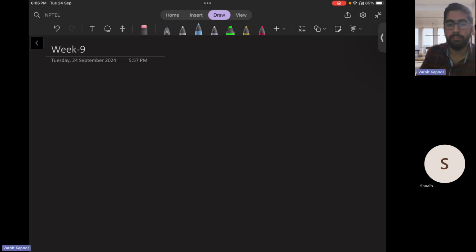in the normal direction. So today we are going to look at the gradient calculations. One of the reasons to calculate the gradients is the requirement of the secondary gradient. It requires the gradient of the dependent variable on the faces. And there are several other instances where the gradients of the dependent variable are required. If you are solving the Navier-Stokes equation, then we have to calculate the pressure gradient. In the Navier-Stokes equation, we have the pressure gradient term which needs to be calculated. And it is not just the gradient in the direction of the face that is required, but rather the gradient in all directions. All the components of the gradient, like the I, J, K components, are required, and not just the direction of the face, which is what the secondary gradient needs.